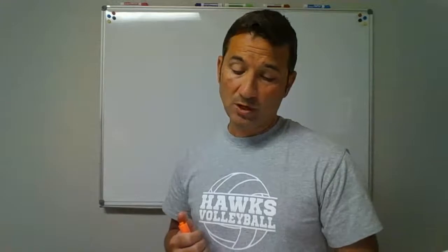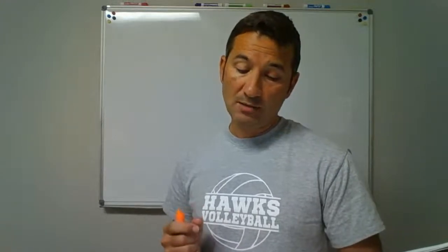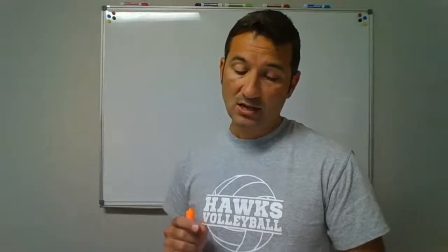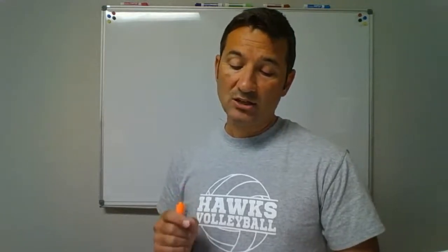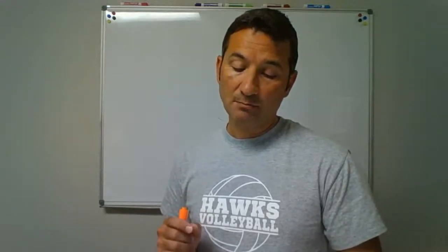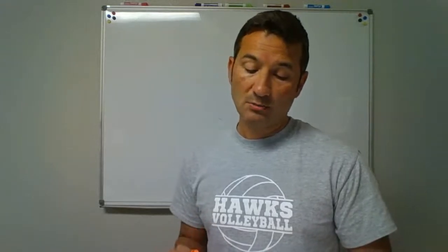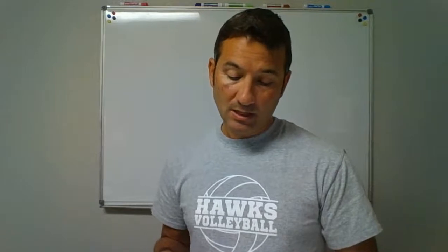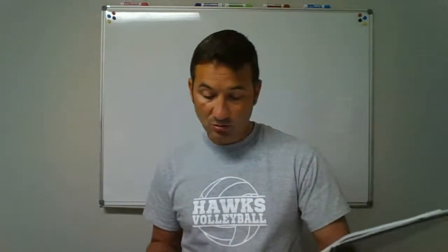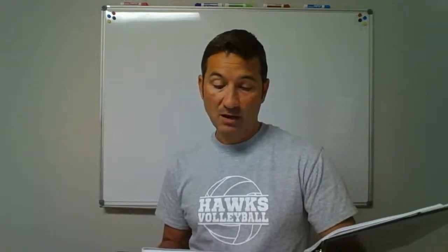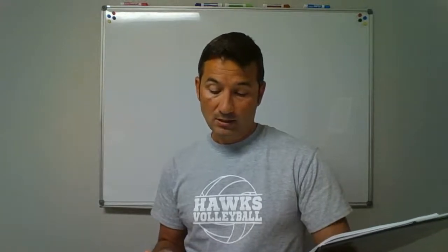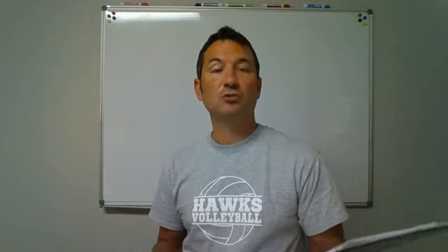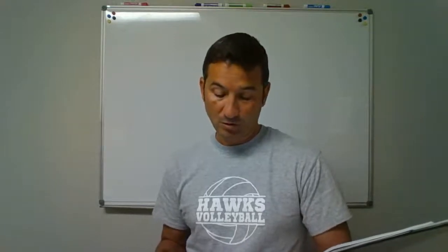The exception: where the manufacturer identification cannot be marked on the pipe fittings and pipe nipples because of the small size of such fittings, the identification shall be printed on the item packaging or on documentation provided with the item. Okay, continue on down. I'll let you finish reading the rest about materials on your own. Get down to section 304 on the bottom of page 15, and we get to rodent proofing.